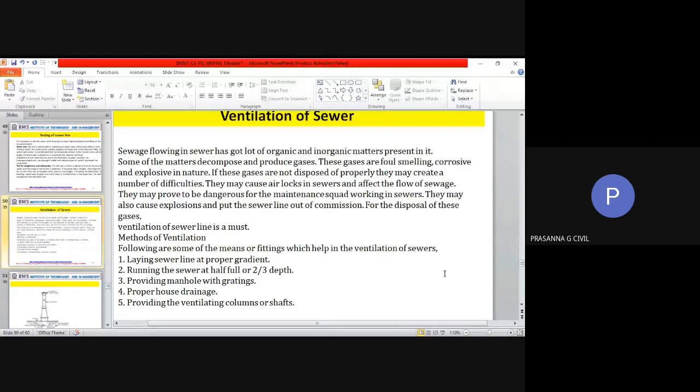In sewer lines, because there is waste water flowing, a lot of organics are present. And these organics are continuously getting subjected to degradation by microbes that are present in the water. And you have so many gases of degradation that are getting generated or built up. So there is methane, there is hydrogen sulfide, there will be carbon dioxide, there will be some amounts of hydrogen